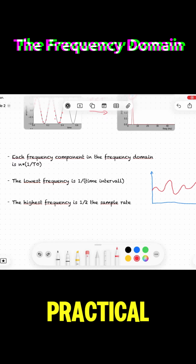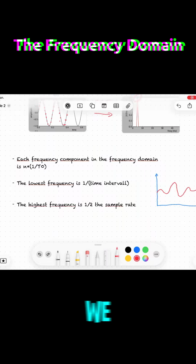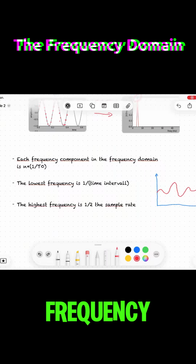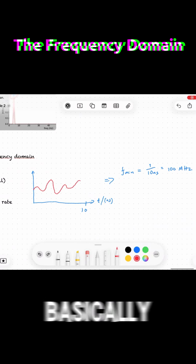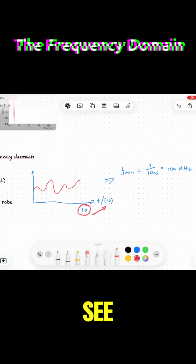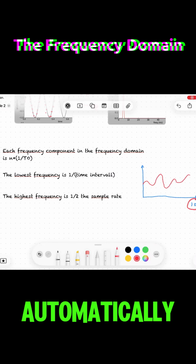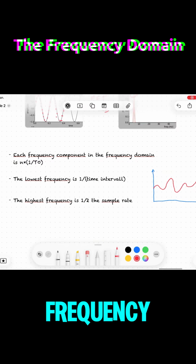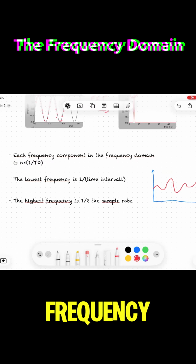There are also practical limits to what we can see in the frequency domain, and these depend on how we sample the signal. The lowest frequency we can resolve is set by the total time window we observe. It's basically 1 divided by the time interval. The highest frequency we can see is limited to half the sampling rate, which is the Nyquist limit. So when we look at a signal sampled over a short time window, we automatically limit the lowest frequency we can detect. And when we sample too slowly, we lose high frequency content.